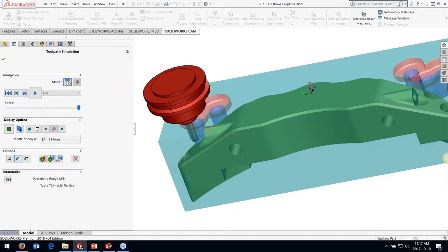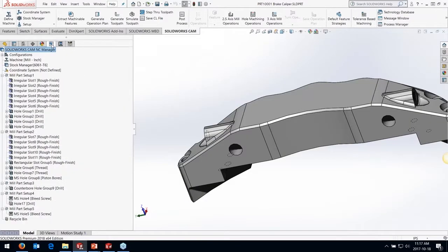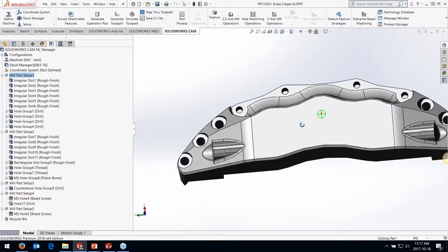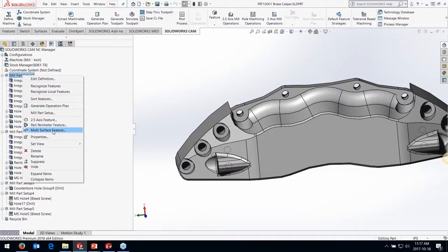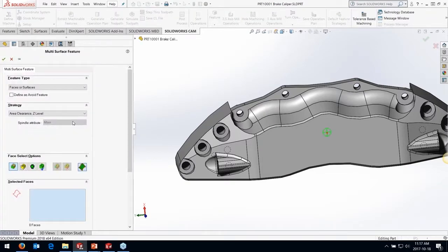Similarly, if I've got things like hydraulic fittings, where I've got a bit more complicated holes, there's actually a hole running all the way through here for passing the hydraulic fluid basically to these cylinders. There's a threaded section, and we've got a chamfer on here. Essentially, it means I can just go and change a strategy in here to say, hey, I've got a bleed screw strategy that goes in and does all of that stuff. Just switch the parameters out here to a bleed screw.